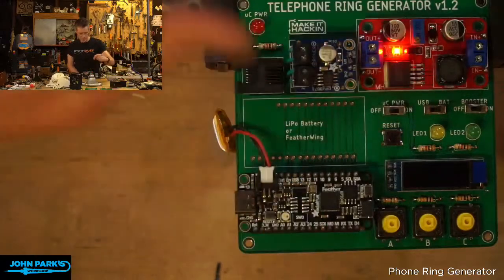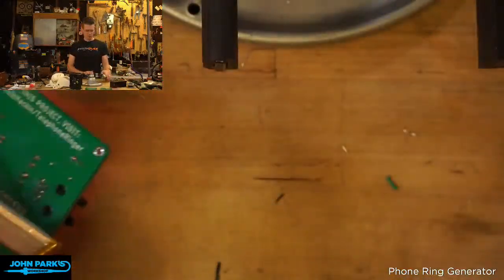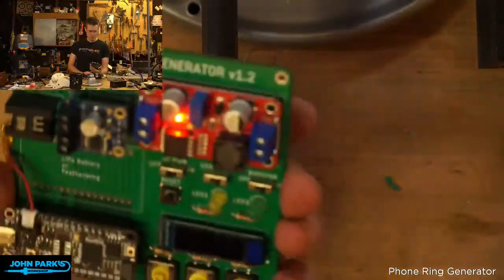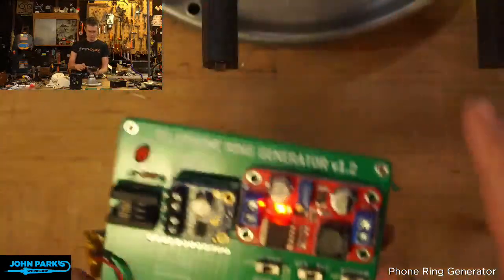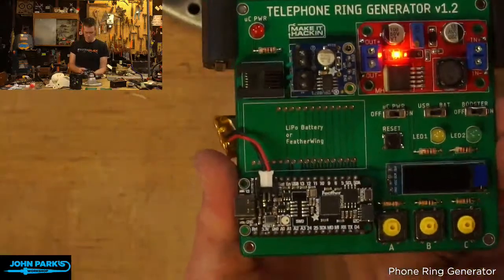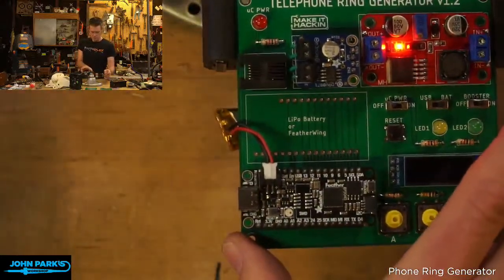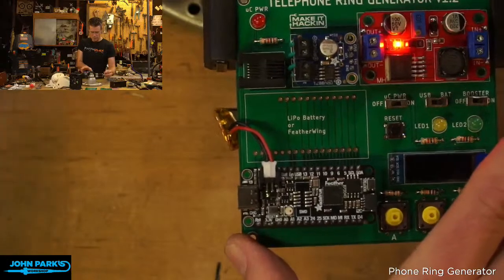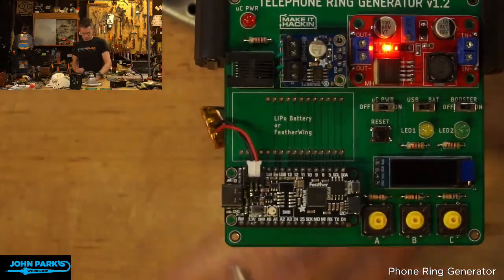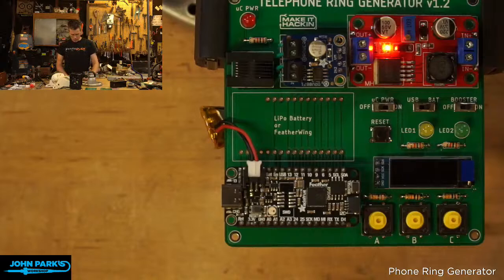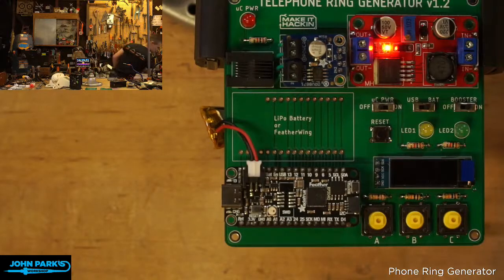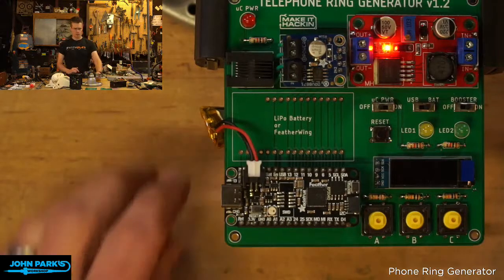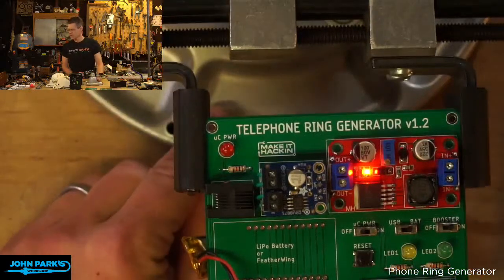One thing I will recommend with these kinds of through-hole projects is before you start turning stuff on, just tap and do this little inspection that you don't have little trimmed leads bridging stuff. It's a really sad way to ruin something, is the trimmings of your through-hole leads are bridging power to ground. Also, another tip is check that you don't have a short between power and ground before you go turning these things on. That was another thing I usually do that I didn't do.